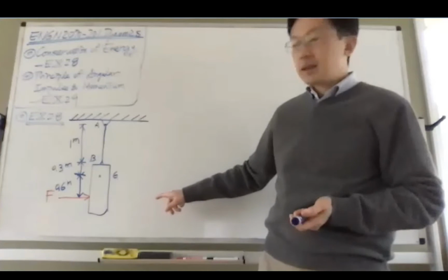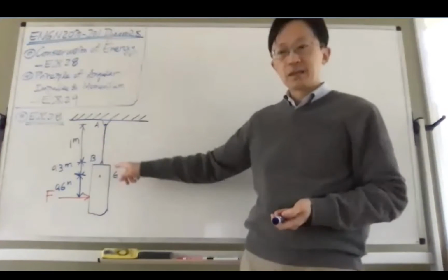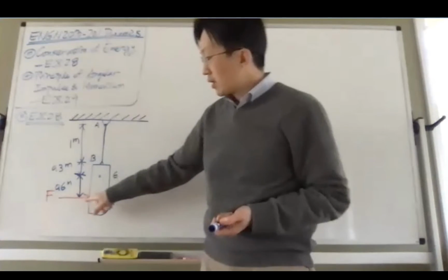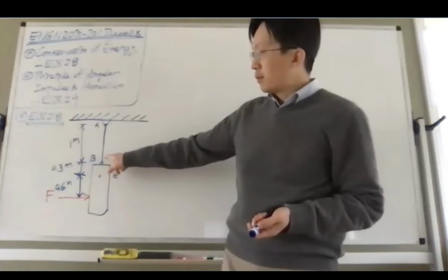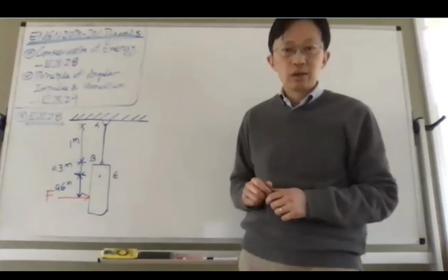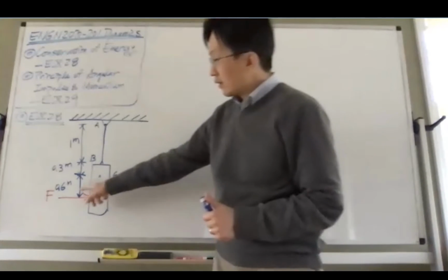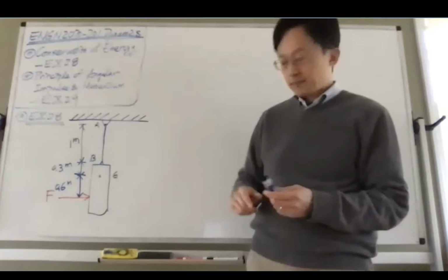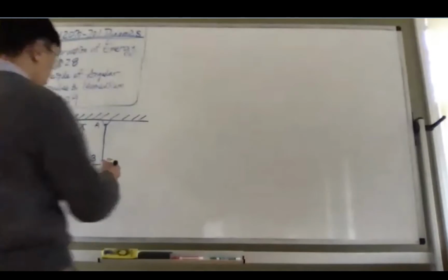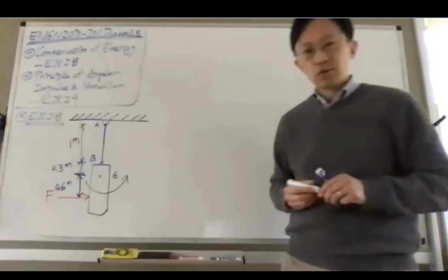In the meantime, because this cable cannot take moment, at the instant when the force applies to the punch bag, point B will be the center of rotation, because you cannot use the rope to provide any bending resistance. That means this punch bag is going to rotate. Therefore, there's going to be an angular motion like this. Would you agree?